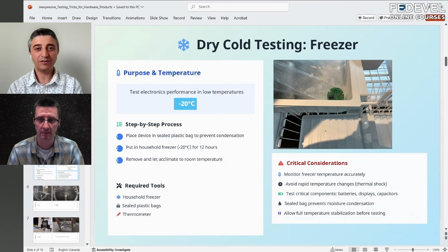In addition to this, the battery is another critical component. The electrolytes inside your battery might be frozen at that temperature. So if you assume your battery is 3.2 amp hours, sometimes you go into the freezer and you will only get probably 30 to 40% of a regular lithium ion battery. Batteries cannot charge below maybe negative 5 degrees Celsius. You're stuck. So if your device is meant to work in an extreme cold environment, then be careful.